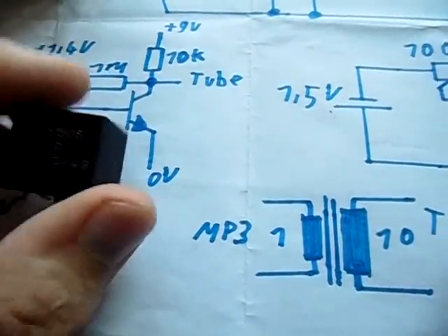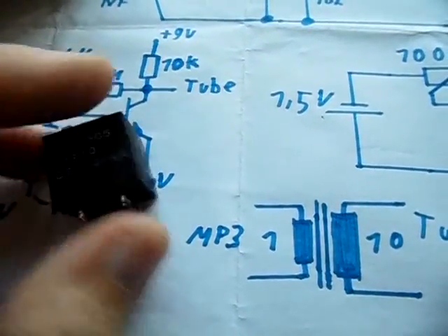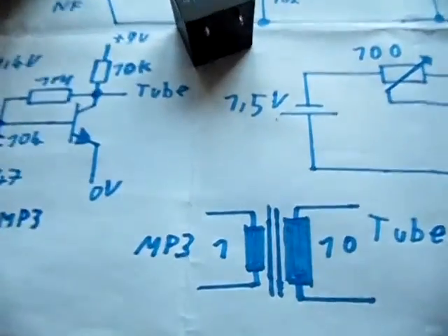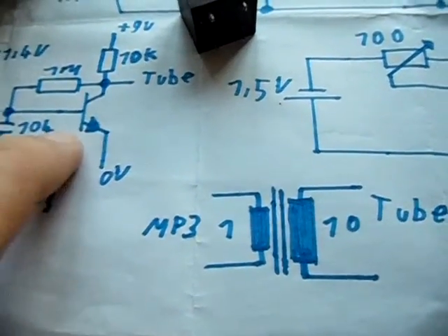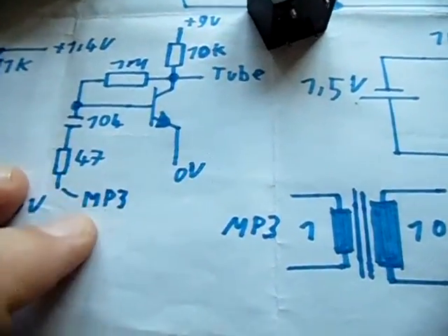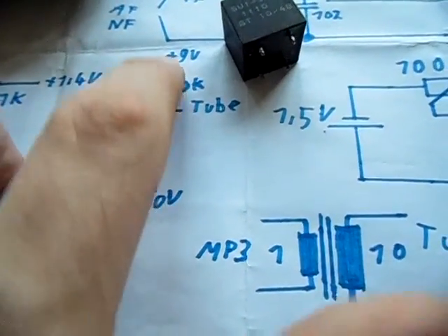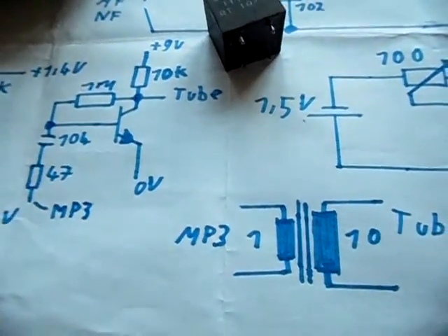The next thing is, since you don't have this transformer and you will be having trouble getting it, and it's kind of let's say weird, I don't like it, you can go ahead and take just a normal NPN transistor like the 2N3904, make this small circuit connected to the filament voltage as well, and then you also have your audio amplifier.